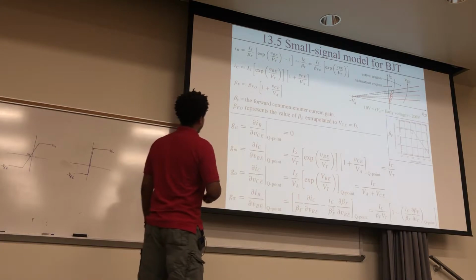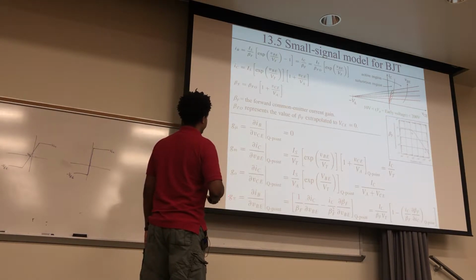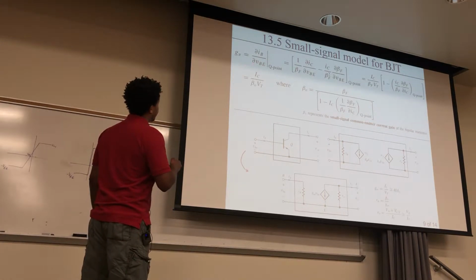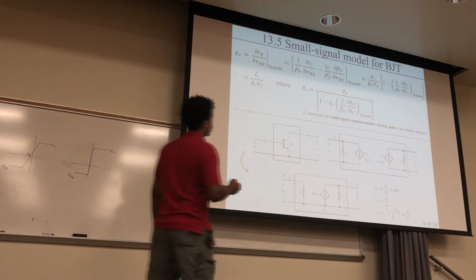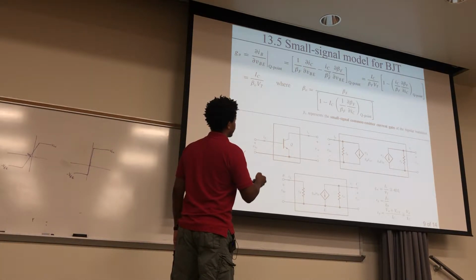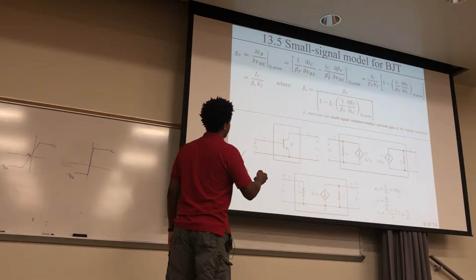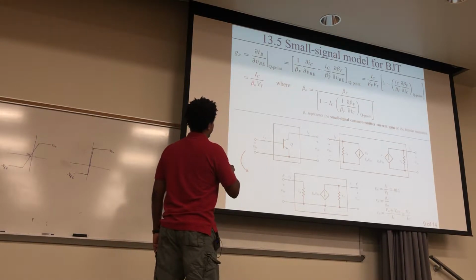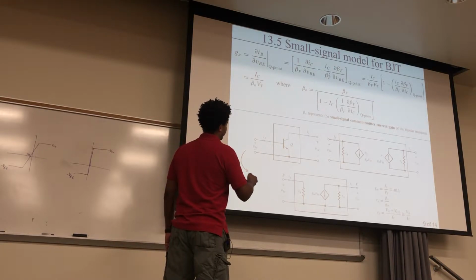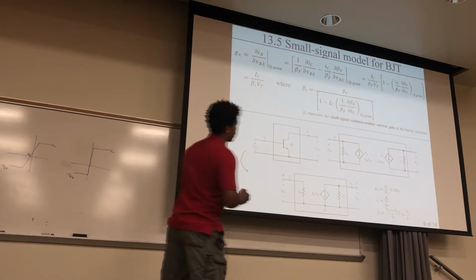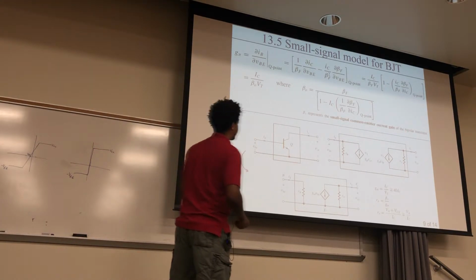Oh yeah, and this transconductance right here, G pi, continues on the next page. This is just some reduction. What the book does is take this expression and group all of this and that beta F into this beta 0. So beta 0 is this expression right here, and this beta 0 represents the small signal common emitter current gain of the bipolar transistor.